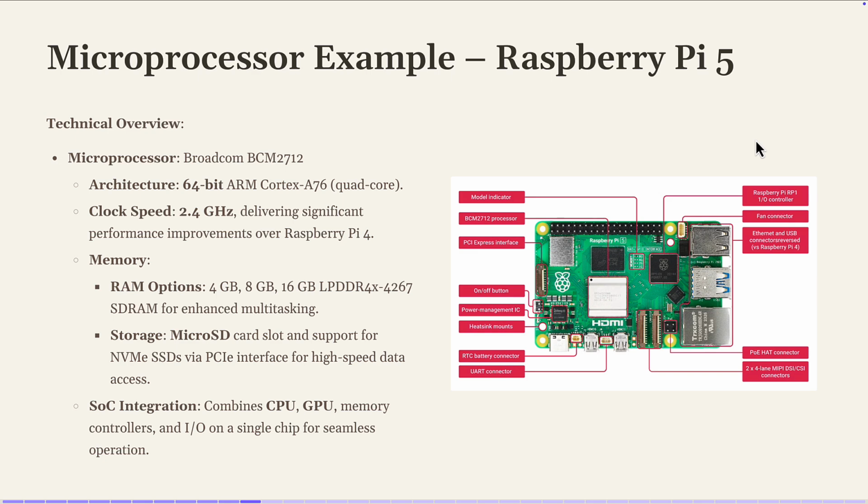How does the processor understand? This depends on the specification of the sensor. It will tell you which level corresponds to which value. Yes, there is usually a conversion. We need to do a conversion from 0 to 1023 into the correct range, because every sensor will have a data range. For example, if you have a range sensor, maybe it can measure between 10 centimeters and 4 meters. So when you receive a value between 0 and 1023, it will be mapped to a range between 10 centimeters and 4 meters, depending on the sensor specification.